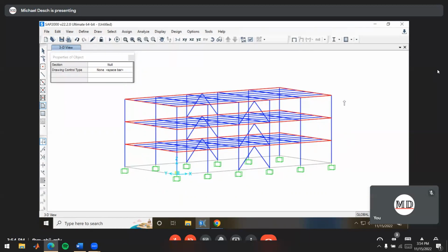And then finally, we'll do that for the windward face of the building. Usually where we put those point loads for the winds, we're going to use an area load today. So we're going to draw one of these areas along this face of the building here, press enter, and we've got it there. Winds are usually applied as a pressure, so let's model them as a pressure today. Any questions on that?